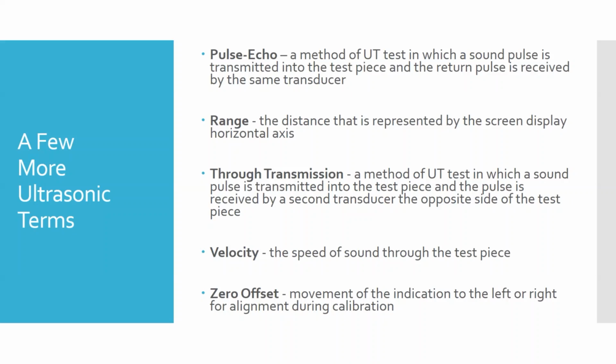If we make that range too big, we're going to be looking beyond the part. There won't be anything of interest there. In fact, we'll get some extra noise called secondary, tertiary, fourth, fifth, sixth order echoes, where the sound keeps bouncing back and forth. It looks like it's traveled a longer distance, but all it's done is gone down and back, down and back, down and back, right? You saw those when I did the slinky. The sound wave didn't just go down and come back to me. If I held it, it could go down and travel back and forth in that medium.